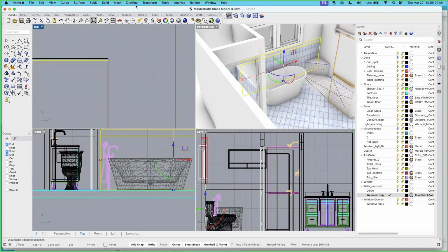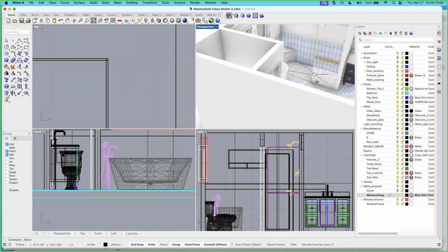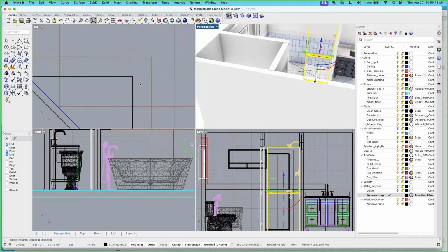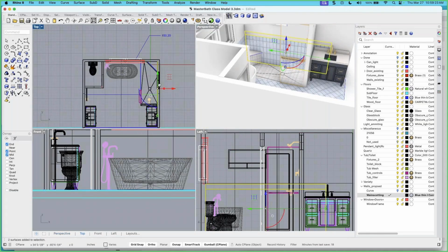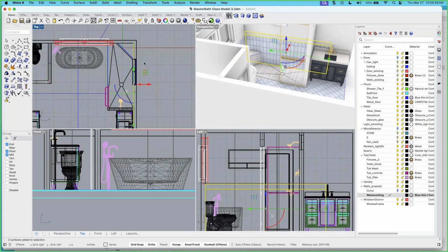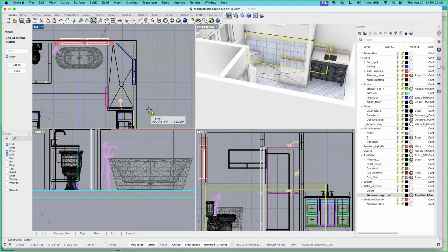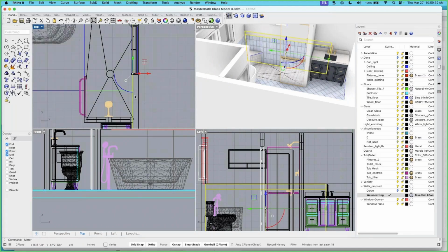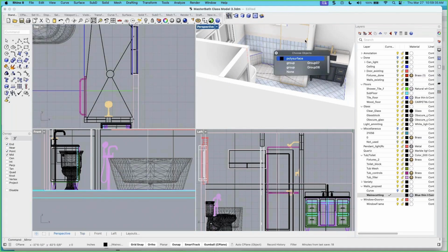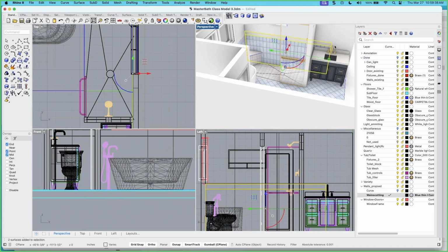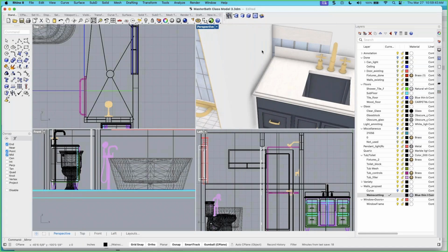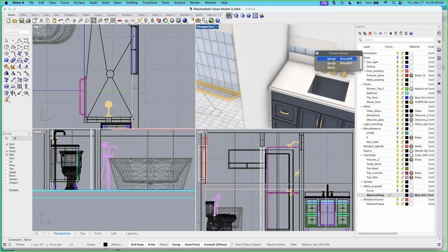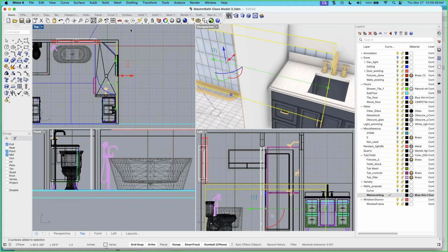Let's go ahead and mirror it. Mirror 45, I think, is a really great way to copy, and that goes a little bit far, so we need to scale this back. And again, scale 1D, or you can use that sub edge selection, whichever you want to do. We just have to make sure, now that we've got the vanity there, let's see, sub-object selection is a little bit more difficult in this rendered mode.